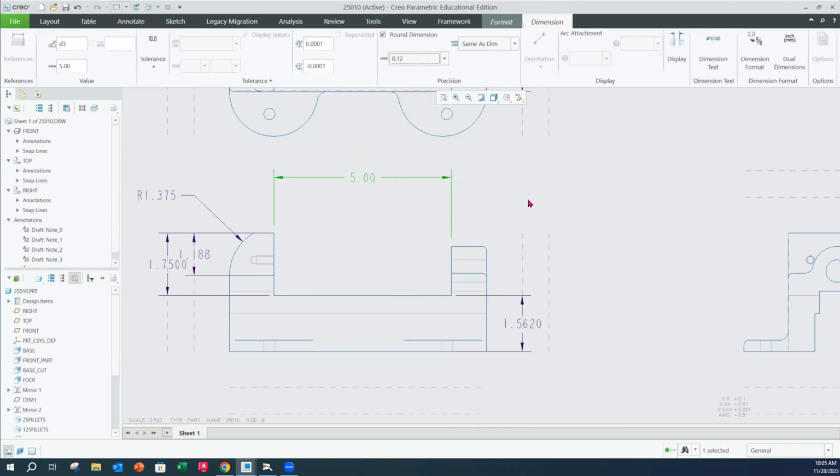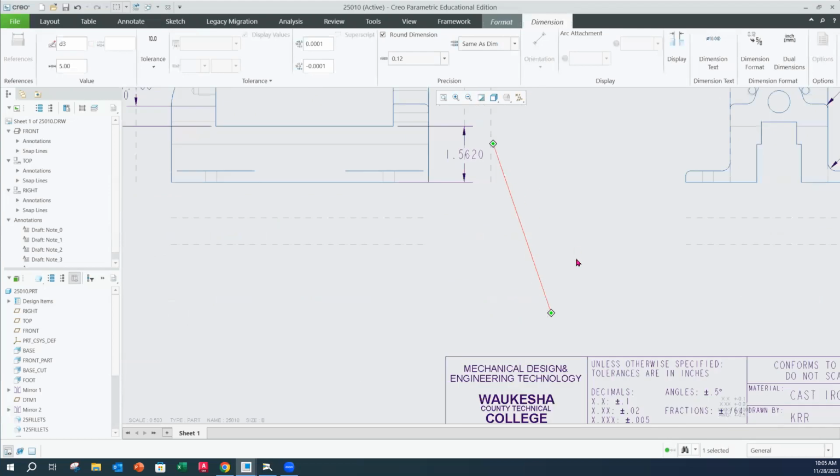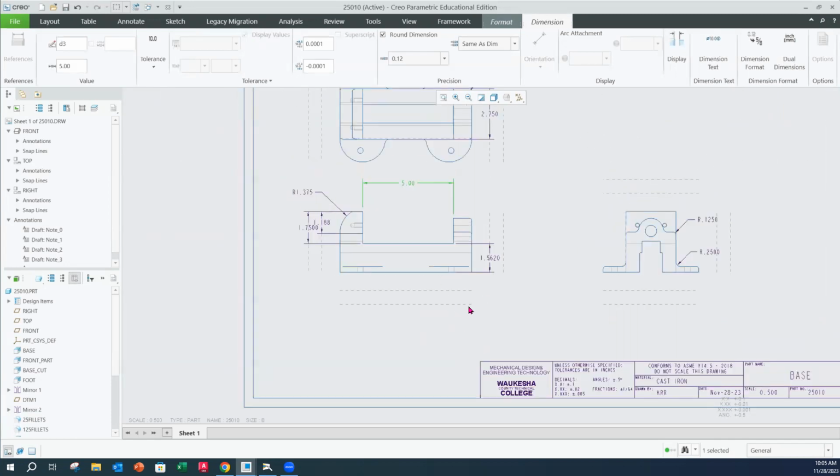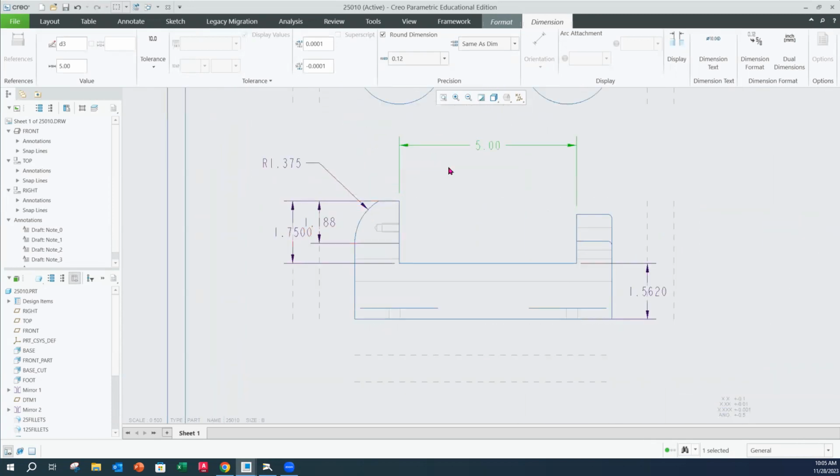Okay. 3 to 2. We always have to be sure, if we're not adding a dimension or a tolerance after a dimension, that it has the ability to and is appropriate for whatever is in our title block. And you could say, well, why didn't you do the 0.1? I'm not doing the 0.1 because I look at this dimension right here, plus or minus 0.1 of an inch. That's a total of 0.2. That's almost a 1/4 of an inch that we're varying for that width. And I think that's pretty extreme. So I'm going to 2 place, which isn't really that accurate. So I just find that better for the application that we have here.